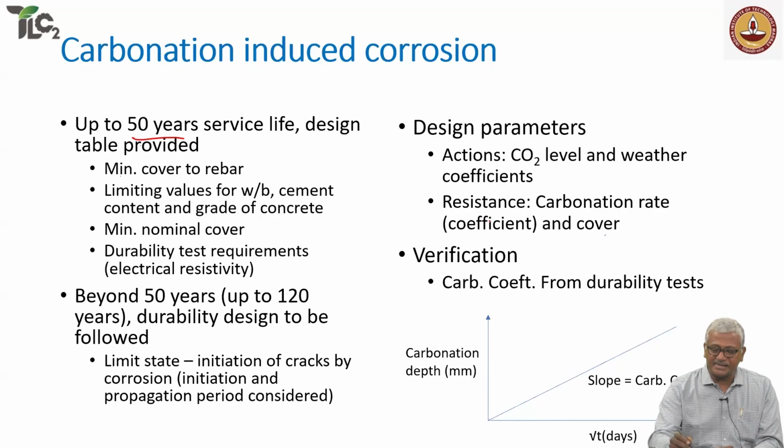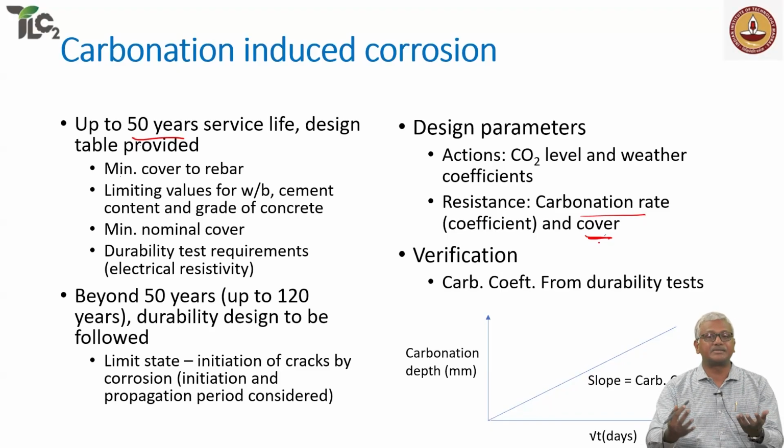Then resistance is defined in terms of carbonation. A concrete which has a lower carbonation rate, a concrete that has a higher cover, will have a greater resistance to carbonation. And verification is through the carbonation coefficient from durability tests done in the lab.